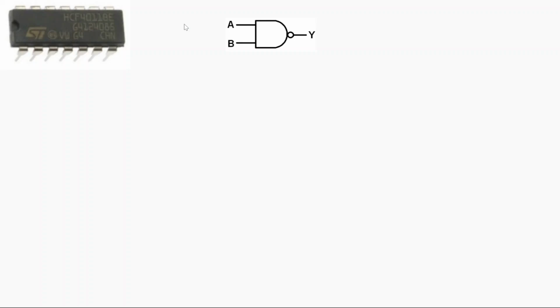But the important thing before building this circuit, I want all the students to know that NAND is the gate which one can use to build any digital logic circuit or equation. So you can make any digital logic circuit or digital equation, same word, same meaning, same concept, by simply using NAND gates. And that is one of the key features of this particular gate.